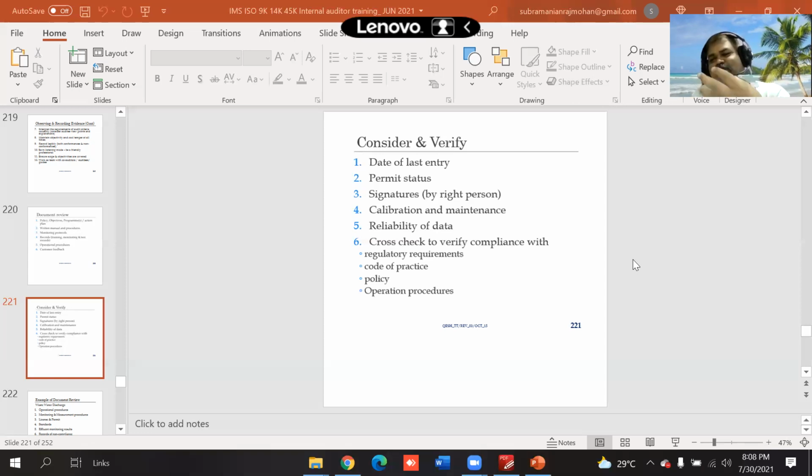So that's how an open question helps you track. Let's say the barricade: no need for a barricade because the height is less than 2 meters. Then we can compare. It is not required, but it is good to have. You cannot issue a non-compliance for this. But this guy is working at 4 meter height with no barricade and no harness. This one is straightforward. It is a legal non-compliance, because of failure to comply with the legal requirements.